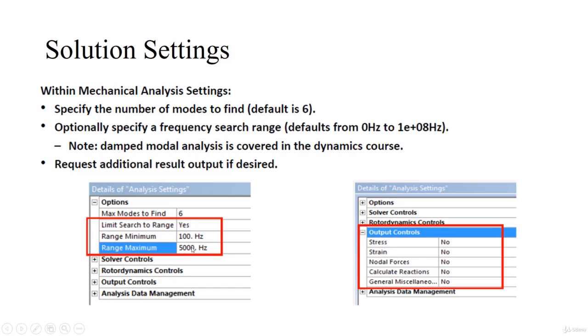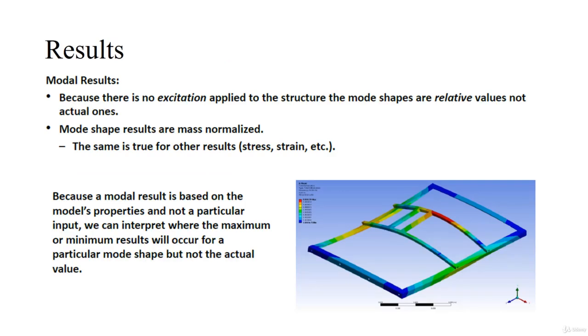In addition to all of these things, I can also ask the software to calculate the stresses, strains and reactions that are occurring due to this particular vibration at the natural frequencies. Then coming to the results, since there is no excitation or other external force being applied, we are going to get the mode shapes as well as the natural frequencies.